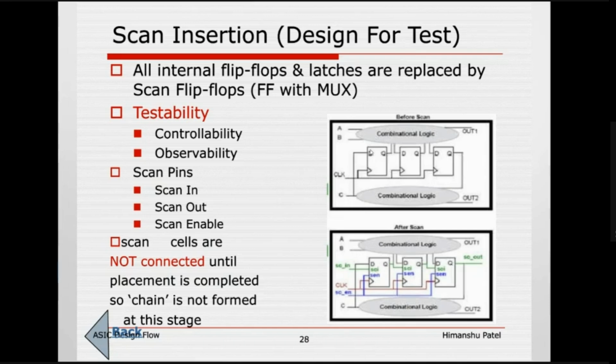Now, when you add a mux here, in digital design, if you want to bypass an existing path, this is one data path, right? Any existing path can be bypassed, and one more additional path can be added on top of the existing path, giving controllability to select the path.